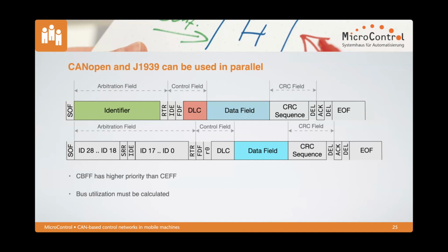Okay, that's clear. But if you take care of the utilization, there's nothing prohibiting the use of both on the same bus. No. They're totally different. That is what people sometimes miss: if you're telling me I'm running the identifier 1 on the bus, I will always ask which one, because the number 1 exists 2 times.